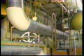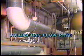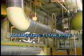Another approach used to measure fluid flow is volumetric flow rate. This approach involves measuring the volume of fluid that passes a specific point in a specified period of time. The simplest way to measure volume is to transfer a specific volume of fluid from one container to another and time how long it takes to do it.